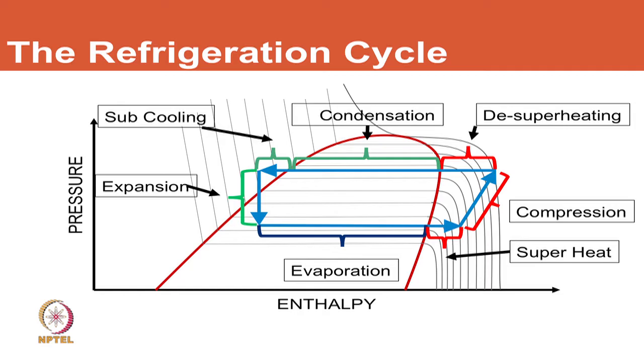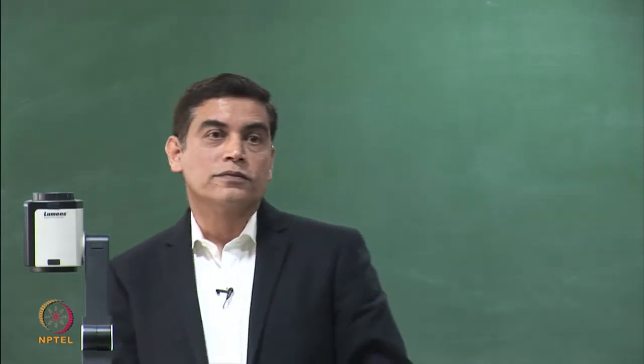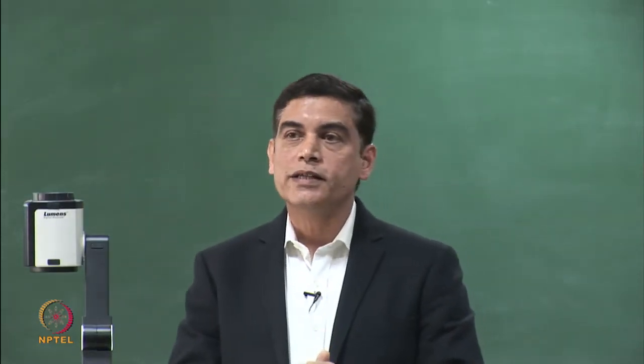Now to do that, one opportunity is to lower this pressure itself, and this pressure and temperature are correlated in the condenser because of saturation conditions. So if we increase the size of the condenser, we can do both: lower the condensing temperature as well as increase the subcooling.